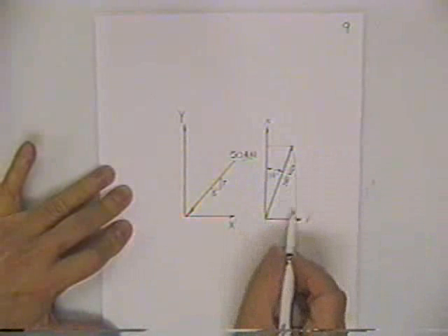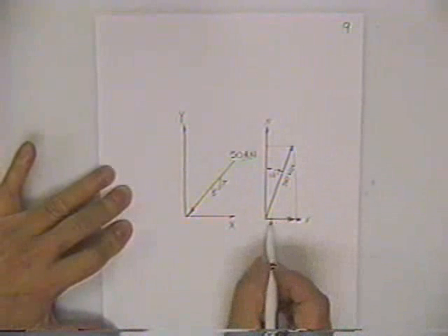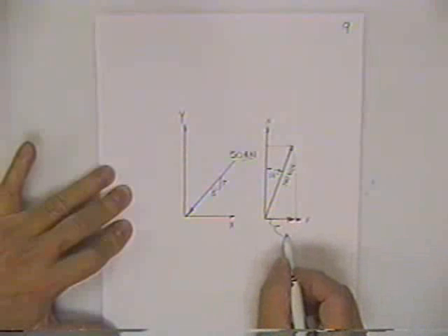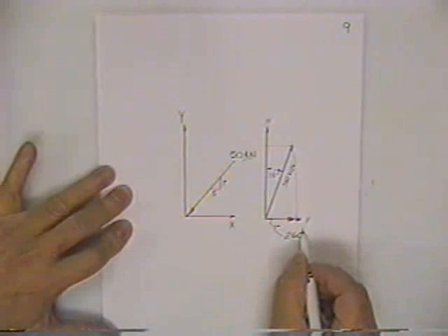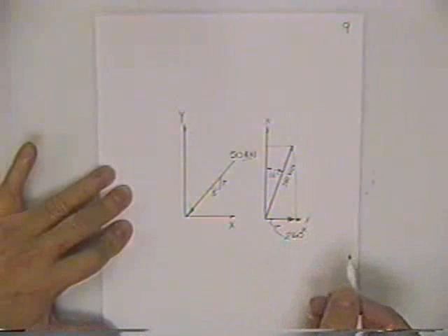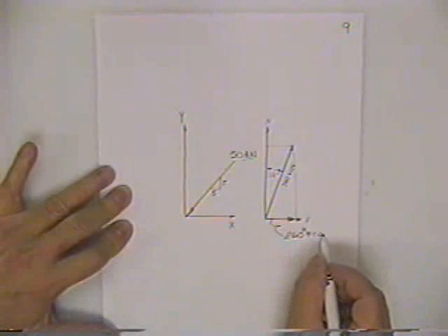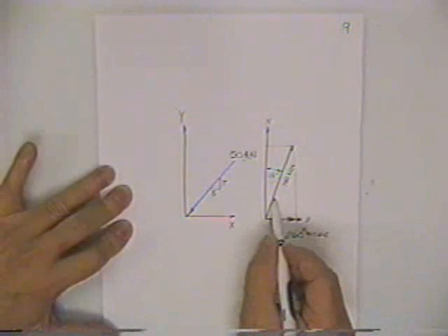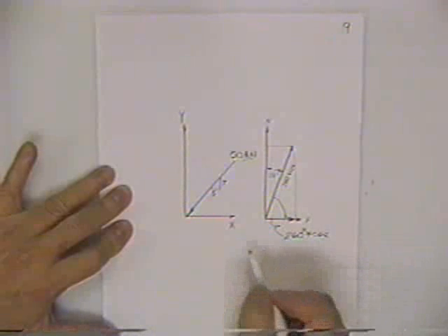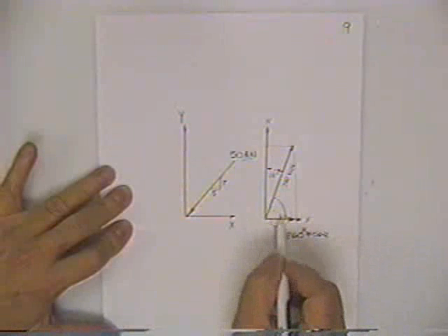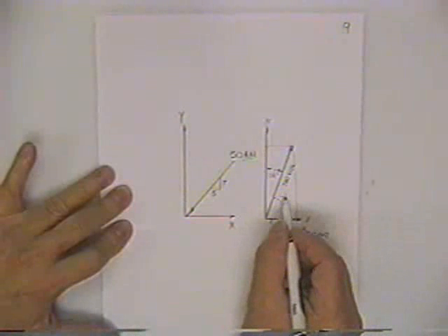The projection on the F-axis could be found by simply multiplying the original force, 260,000 pounds, and then you multiply that times the cosine of the included angle between the force and the axis that you have been asked to find that component. So since we've got 90 degrees in a right angle, we're talking about 72 degrees.